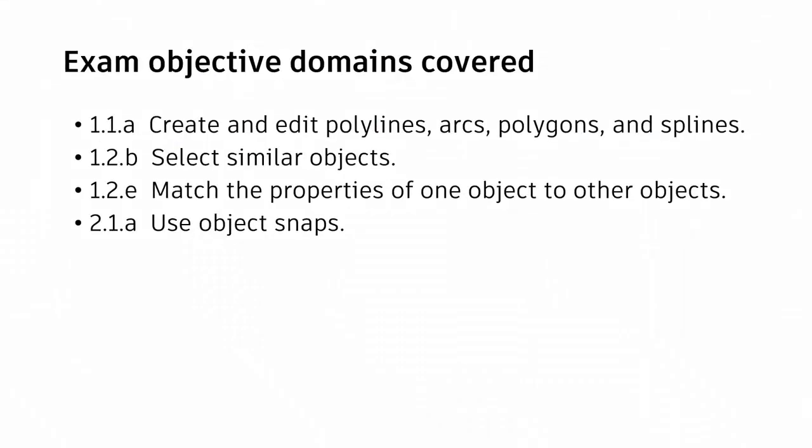We've reviewed different methods to create and modify polylines. We used Polyline Edit to convert lines to polylines. We used match properties to ensure that our polylines use the same width. And we used the boundary command to create a polyline outline of our area.